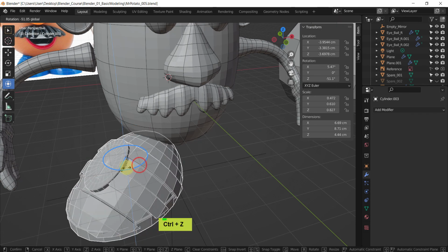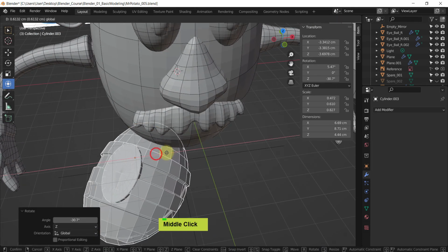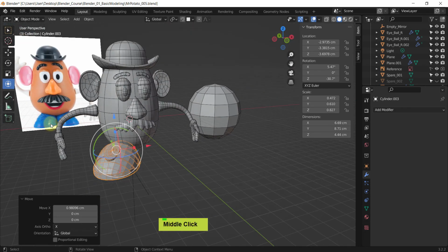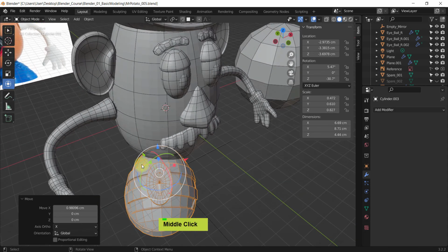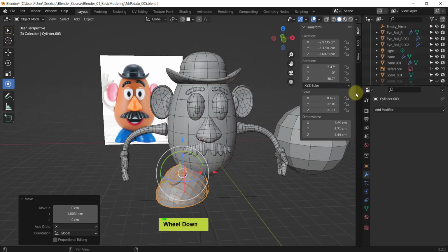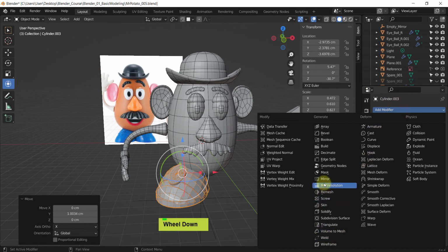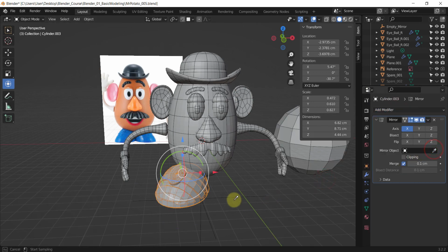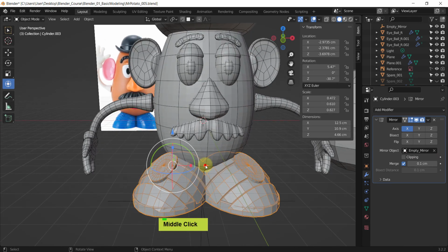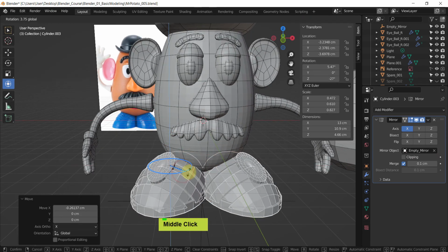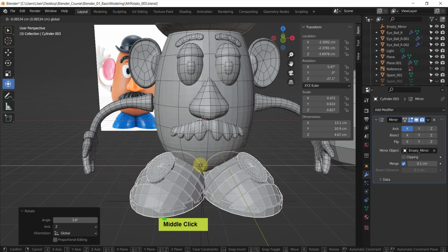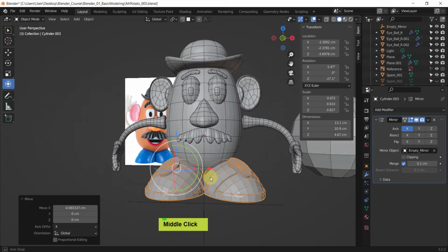Sorry, wrong axis. So this is it there, and I'm looking for the center, so based on the image these will weld anyway, so we can weld them. There we are. And modifier is mirror modifier, the reference point is this one, so it's welding now. Of course, if I want, I can make corrections, but these are welding anyways. Right, so the figure's sitting right there. Cool.